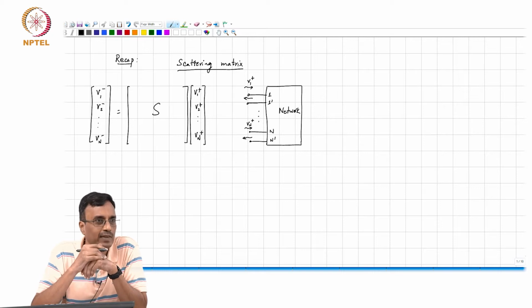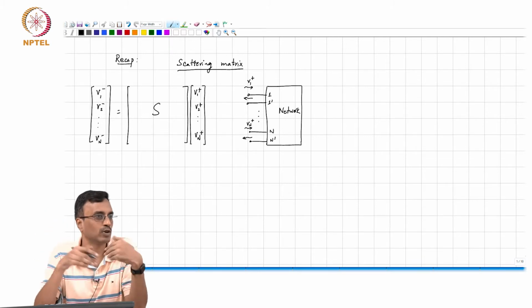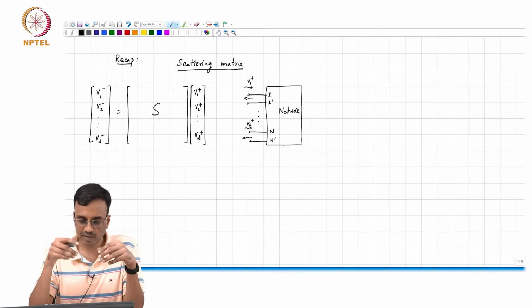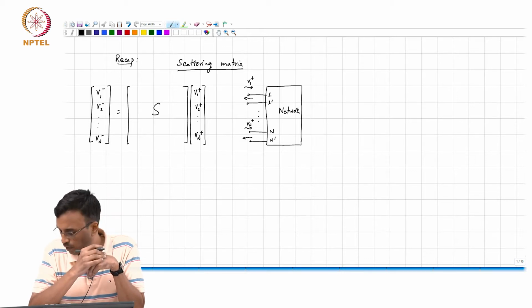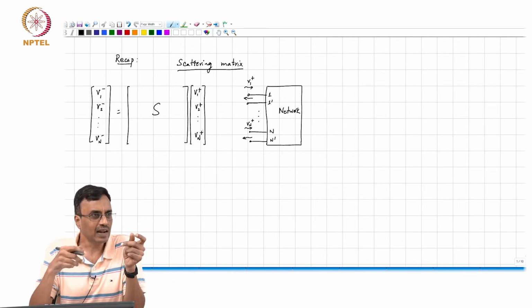The worst case, of course, is that the amplitude of oscillation becomes so large that the power dissipated in the transistor becomes large, or the voltage across the transistor and the current through the transistor become so large as to breach its maximum permissible voltage and current values, and that will cause destruction of the transistor. And sometimes if the transistor is a large high power device, then it is entirely possible to have an accident.